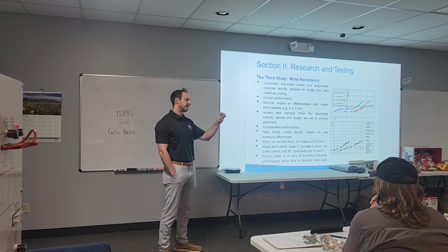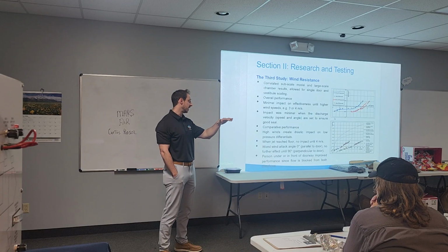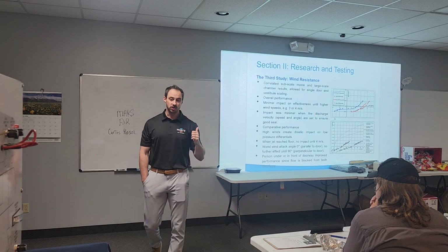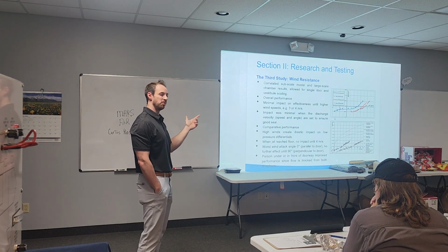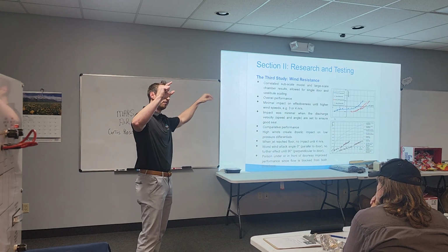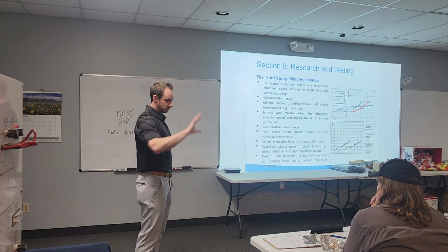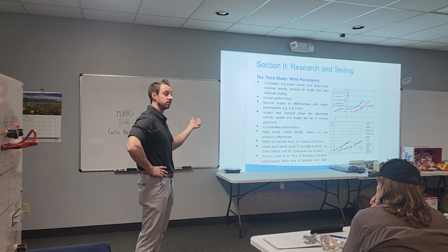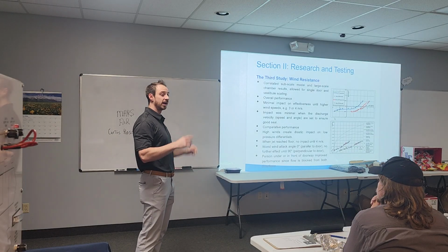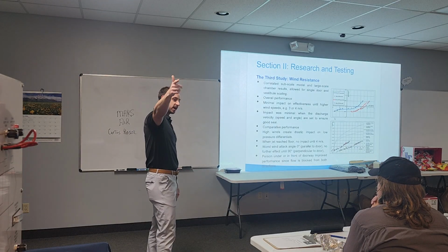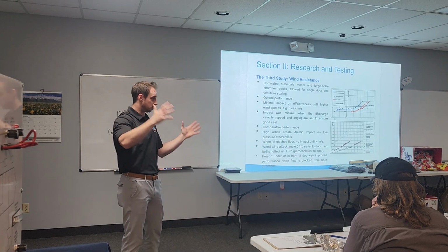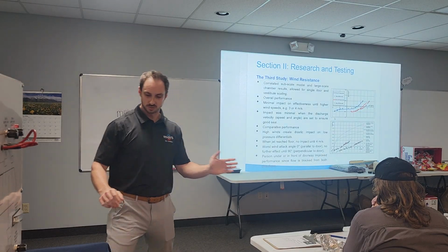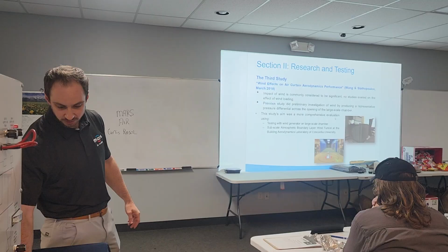But again, tying into that negative pressure, if there's a wind tunnel effect, you're going to have kind of the same issues. So we can install air curtains. A lot of times it's in production type plants where they'll have a front door and a back door open, creating that wind tunnel effect. If you install air curtains on those types of projects, make them aware: if the door is open, you've got to make sure the back door or whatever is closed, so we're creating that pressure chamber and not getting the negative pressure through the building.